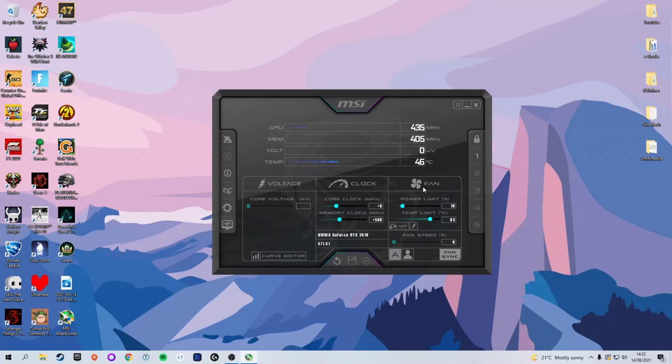You can tune the memory clock and core clock slightly to see if you can get more performance out of the card, but this is what I like to leave it at. WhatToMine have done testing on this, so I trust that this overclock will be stable, and it's what I'm going to run to continue to mine with.